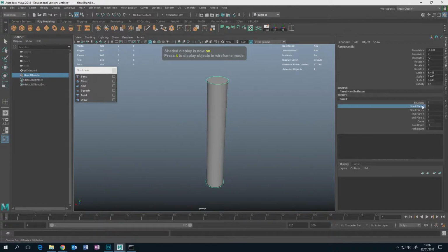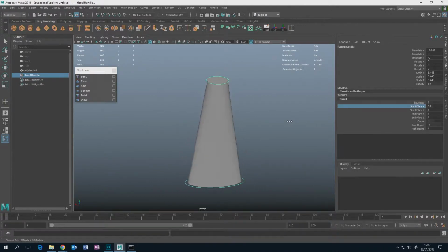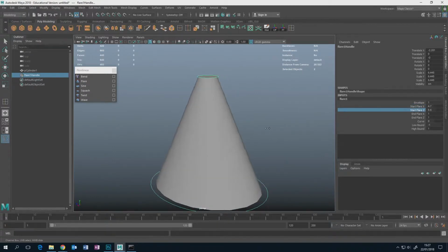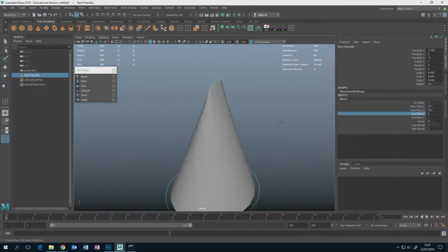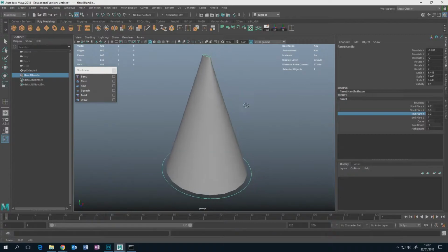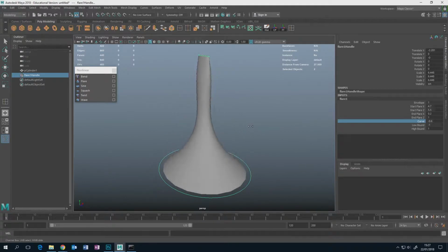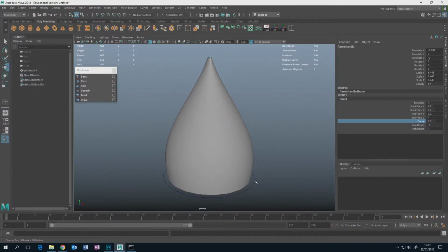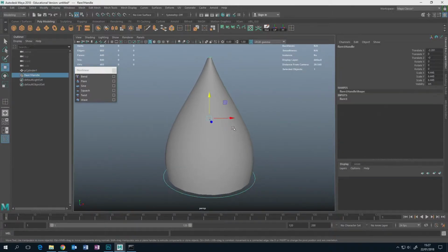Nonlinear deformers exist here in Deform, and there's just loads. Again, concept artists are going to touch virtually none of these ever through their entire career, unless they inexplicably decide that they want to suddenly become animators or something, because a lot of these are animation kind of tools. The only ones we're really interested in are in here, non-linear. Again, if you don't know this, see with this little dotted line here, if you click that, it kind of tears away the menu, so you can have that menu hovering. You don't need to go back up here. You must have an object selected, or if you hit one of these, it will just error out.